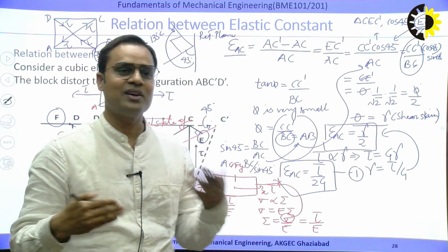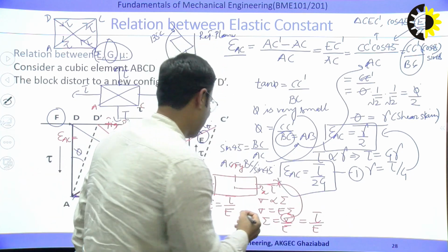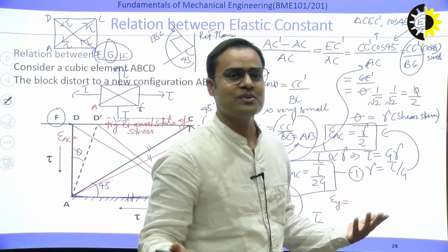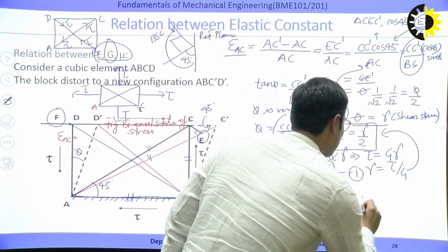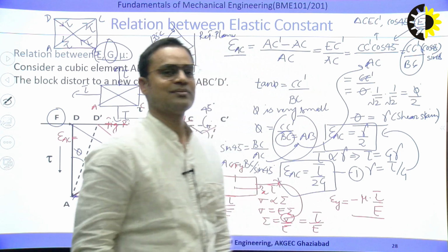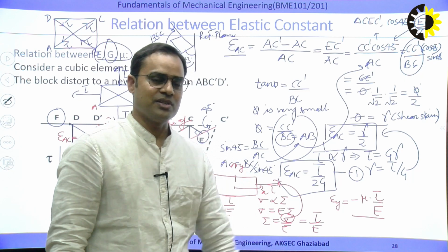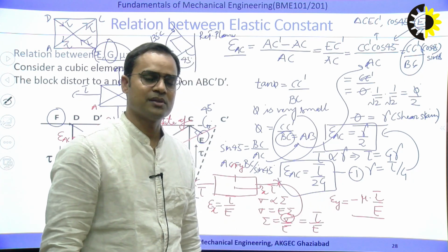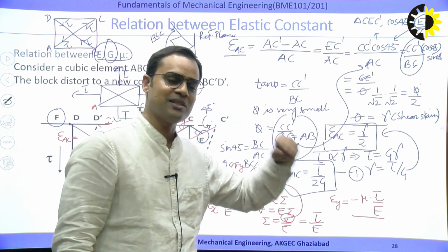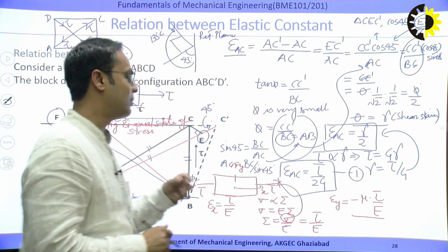And how much strain in the y direction? That is the lateral dimension. How much strain in the lateral dimension? So that is the epsilon x. How much strain in the y direction? Just as we have seen, minus mu times longitudinal strain, and the value of longitudinal strain is sigma x by E. In the previous derivation, we have seen these things many times. So this much is the strain induced in the x direction, this much is induced in the y direction. And now I am considering the biaxial case.